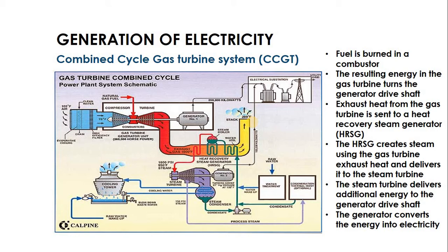That tells you that though the exhaust pipe is only channeling the product of the combustion from the engine, it is also very hot. So if the exhaust from the simple gas turbine can be very, very hot, instead of allowing it to just go waste, why don't we use the heat in the exhaust to also boil water to produce steam, so that steam can be used to generate more electricity?